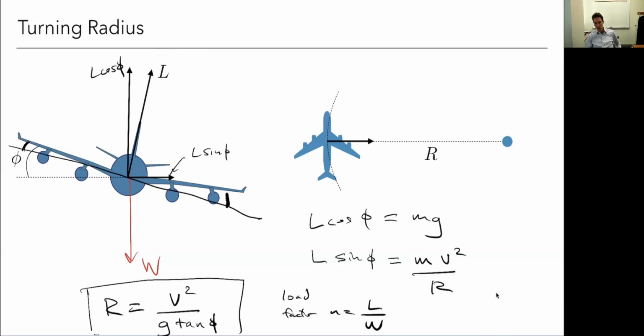And of course, that's related to this bank angle, although for transport aircraft, we're not going to pull these high g's. But if this was like a fighter and I had to pull a really big bank angle at a steady turn, that could be one way where I'm introducing high g's. And of course, if I do a steady turn while also doing a pull-up, then I can get to really high g's. We'll talk about these load factors again a little bit when we talk about structures. But for now, just thinking about turning radius, there's a fixed range we can go to here. So from an aircraft design perspective, our main parameter that's going to help us get tighter turns is to be able to decrease that stall speed if that's something that we need to do.